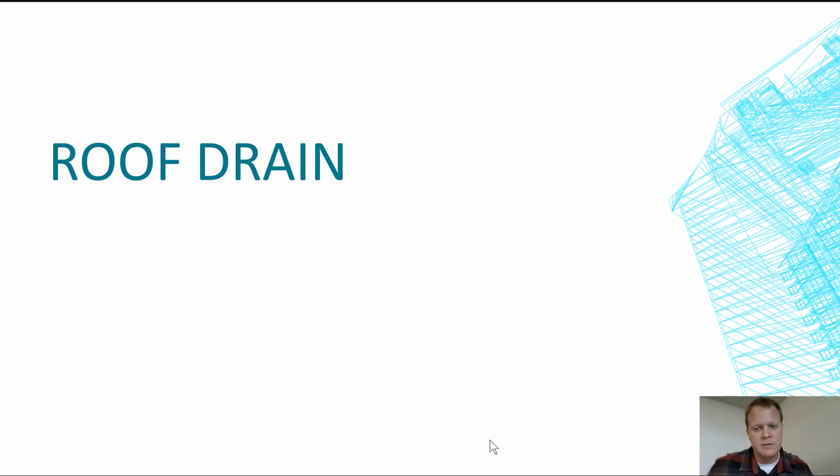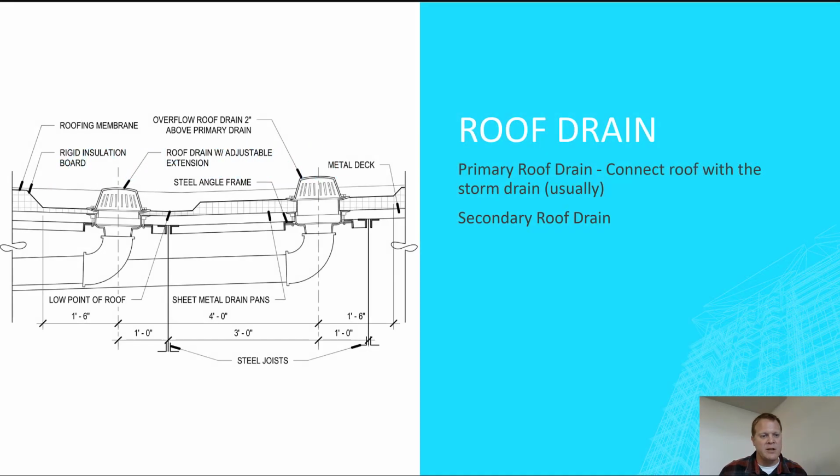We've got roof drains. I've talked about this in the previous lecture, but I pulled out a good detail this time to try and show it rather than me draw it. We've got this drain body right here with a basket over it, and this basket keeps the lighter debris from getting down into here. This drain body is attached to the decking in this case, and then we've got piping coming over this way, and we've got roof deck and insulation.